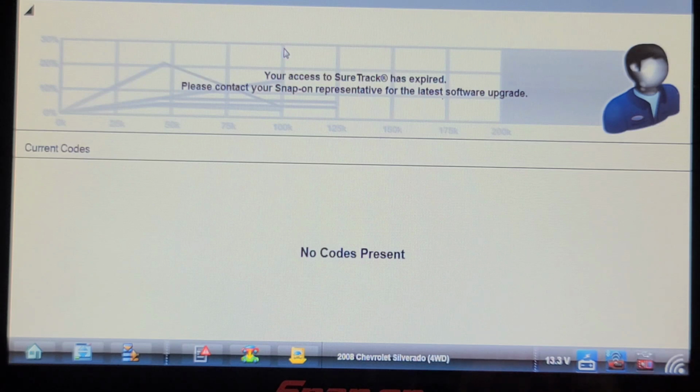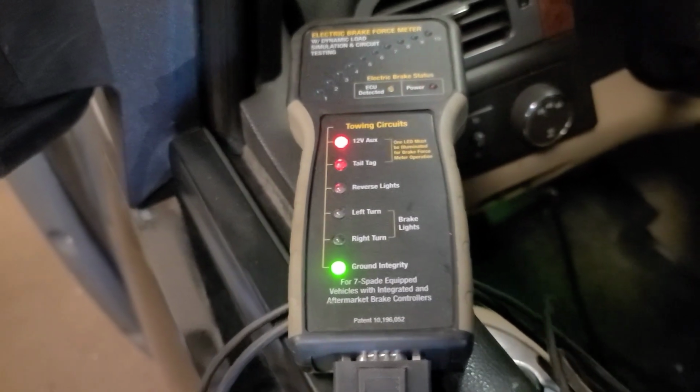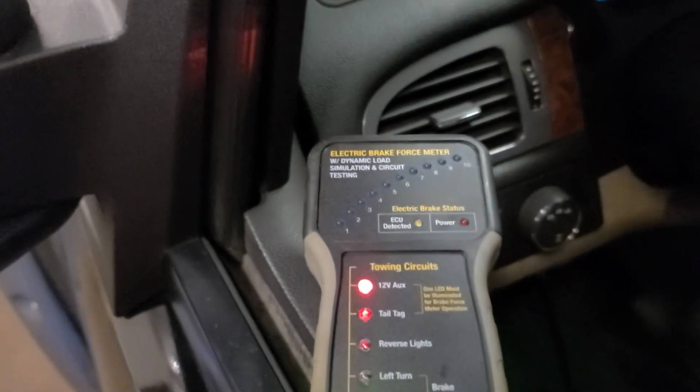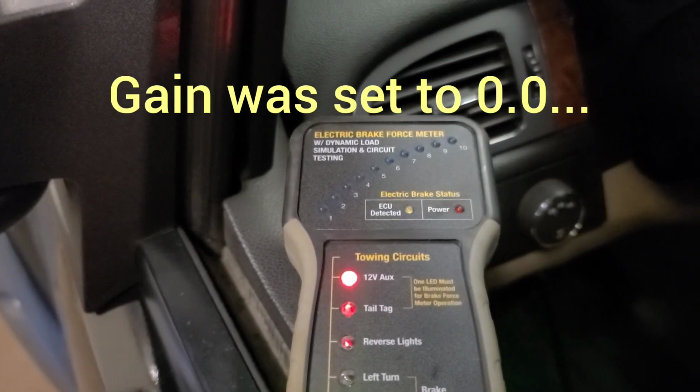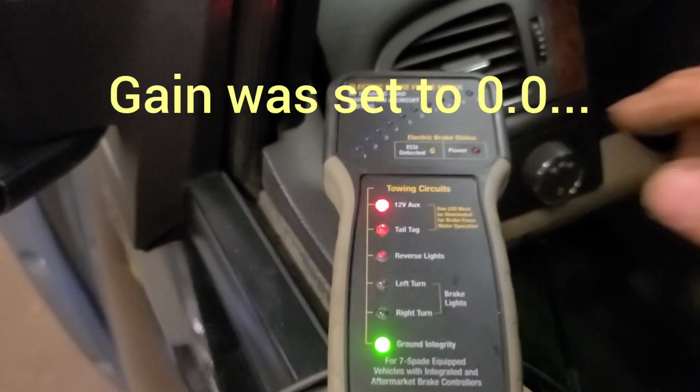Let's plug in that trailer brake plug and use the circuit tester on it. So here's the electric brake force meter connected. Don't have any messages on the dash and no fault codes in this. But when I operate the trailer brake control, nothing happens. Let's cycle the key. It's not detecting the ECU.